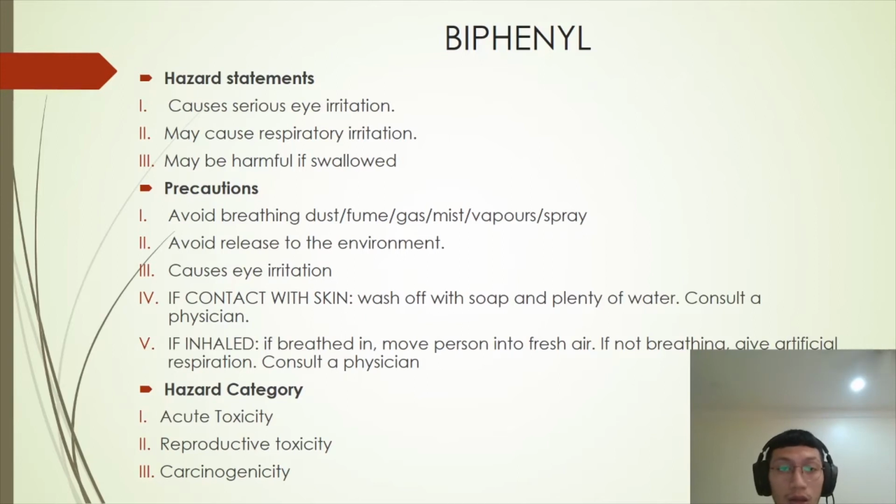Thirdly, it causes eye irritation. Okay, if in contact with skin, we have to wash it off with soap and plenty of water. If it continues to irritate, consult a physician. Then, if it's inhaled, move the person to fresh air. If not breathing, we have to give artificial respiration and also contact a physician.